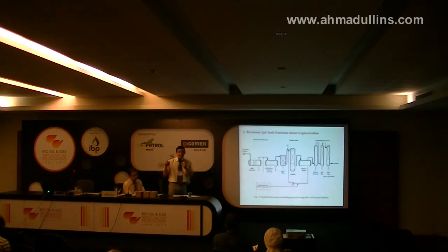So that was the technology for the demercaptanization of light hydrocarbons. The next technology is for demercaptanization of jet fuel. We call it kerosene sometimes. With the putting into operation of hydrocracker refineries, there were significant amounts of desulfurized kerosene fraction. This makes it possible to increase the production of jet fuel through the involvement of virgin kerosene fraction by manufacturing composite jet fuel TS-1 for Russian standards and Jet A-1 for international standards.